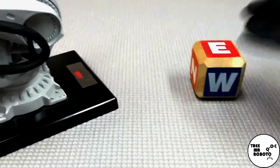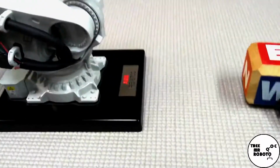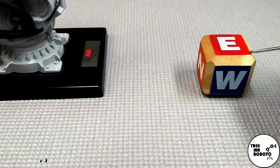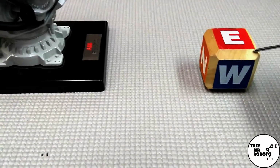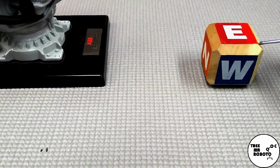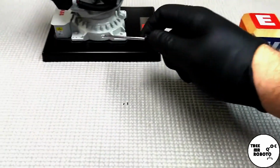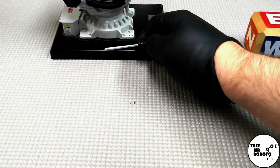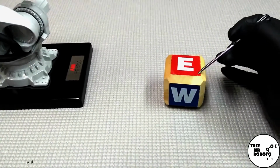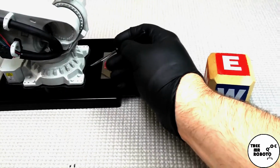So if you have the base of your robot in this location and you have your fixture over here, when you teach this origin, you're going to show 6 different values. You're going to have an X dimension offset, so that would be the dimension from here over to here, right? And then you would have a Y offset, which would be the dimension from here over to here, okay?